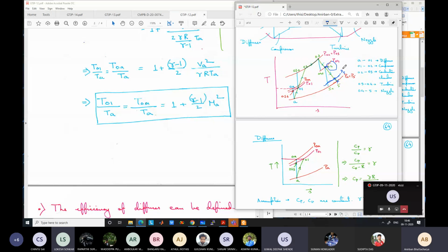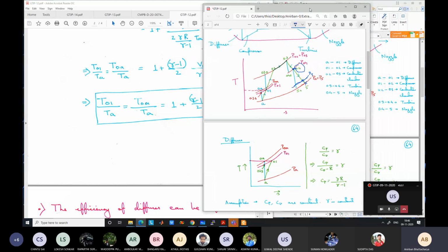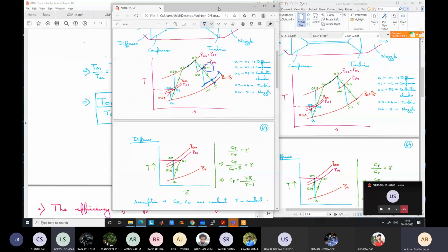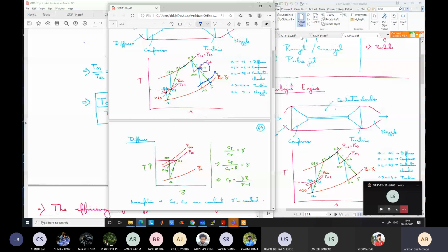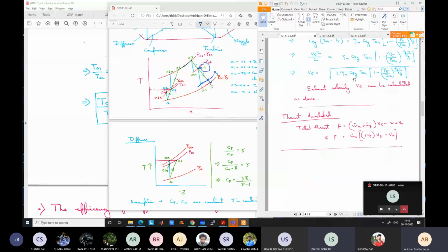Sir, the kinetic energy is gained based on the pressure drop, right? So we need to know what the pressure drop is. That is gained based on the pressure drop, but that is already related to the temperature drop also. Everything is related, because from the temperature directly we have calculated the velocity. For velocity calculation, we don't need the pressure drop in this case. But the pressure drop is still needed to calculate the pressure thrust. Correct. There is a second term in the thrust.